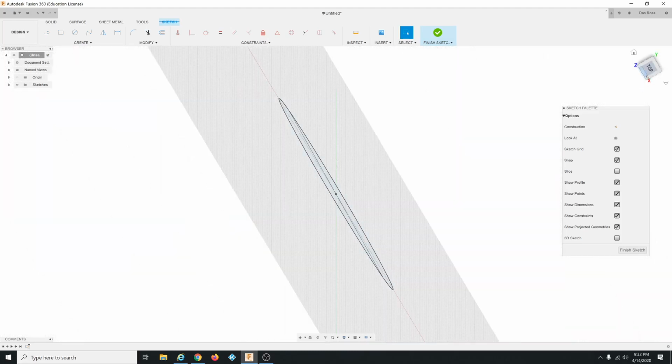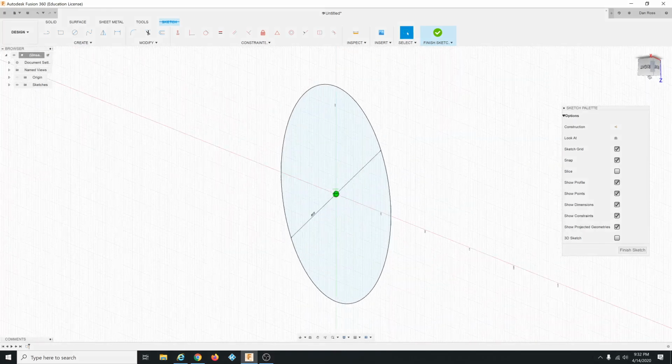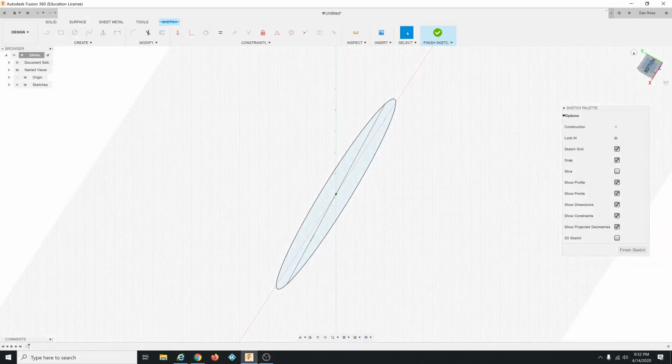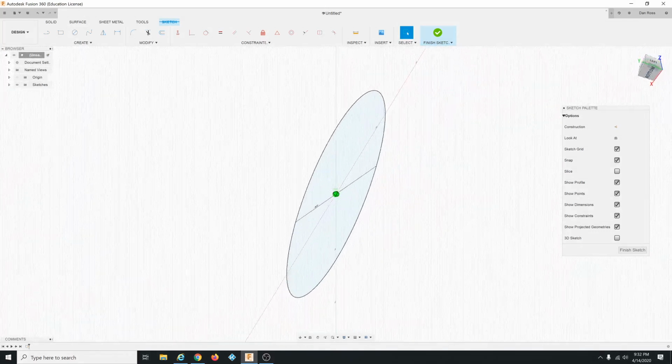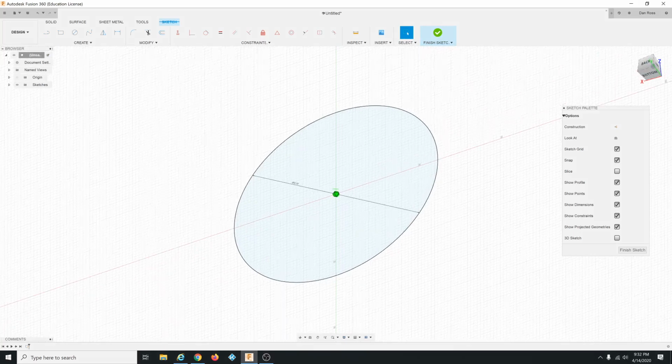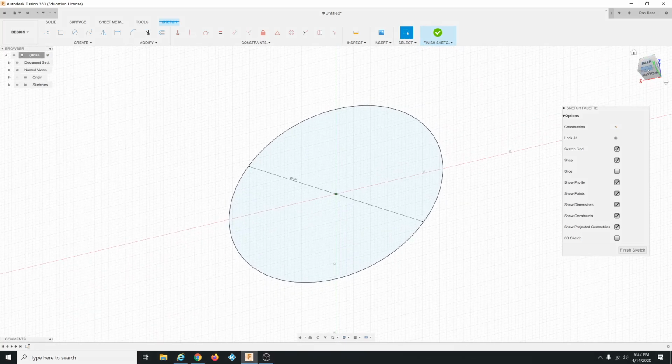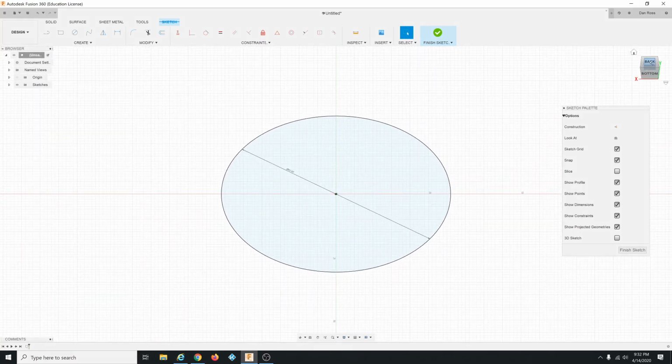What's in the tutorial is, drag this cube around until you see back and bottom, and then click the edge between them. That's what's in the tutorial. Now go over here to this drop down arrow, and where it says set current view as home, fit to view, click that.